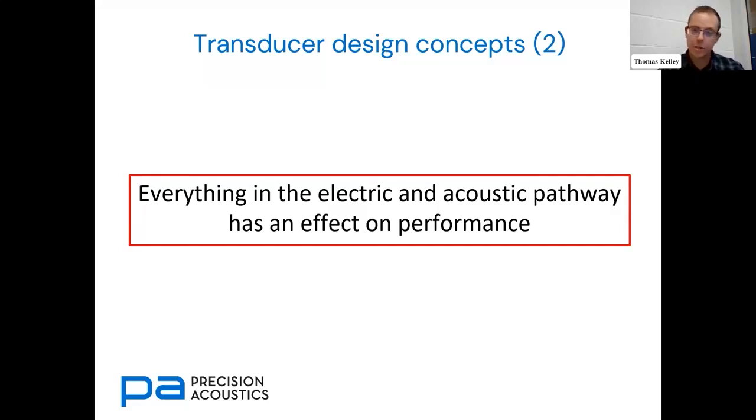So, right from the initial drive signal, through all the cables, connections, through the transducer itself, the backing, the piezo, the matching, into the load medium, everything has an effect. And you must consider all of this together to really get the full picture of what your transducer is going to behave like.